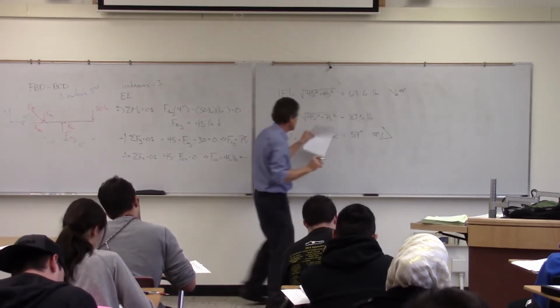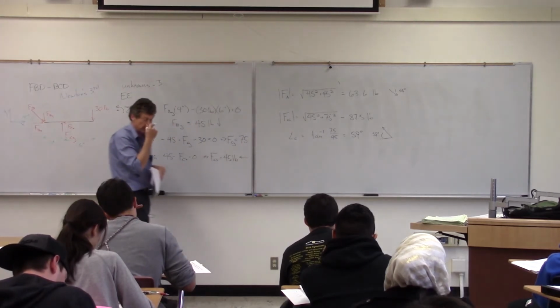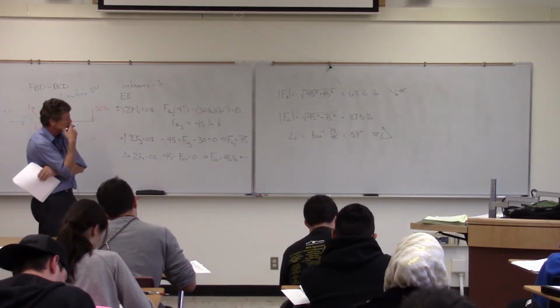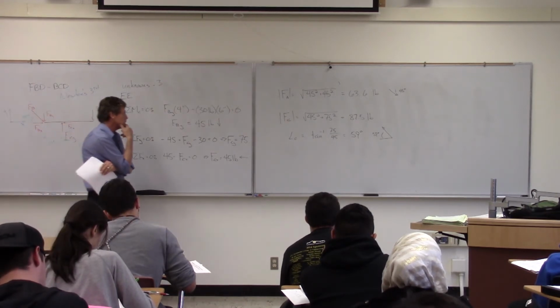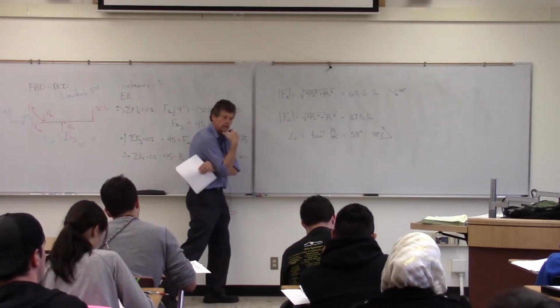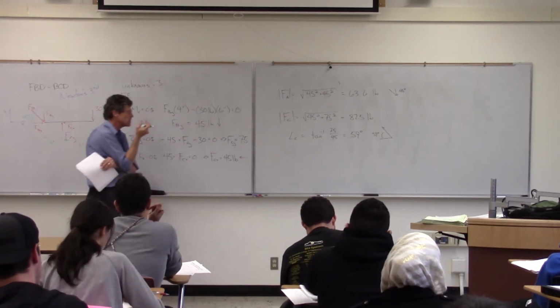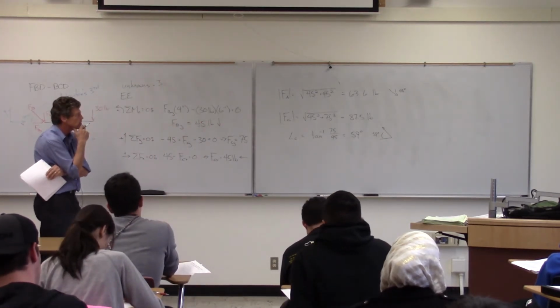And then the full load acting on that pin C, or at that support, is going to be 87.5. Going through the calculation, rise over run, in this particular case, we'll find that it's about 60 degrees in terms of the force acting there.